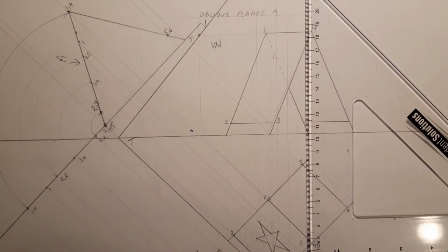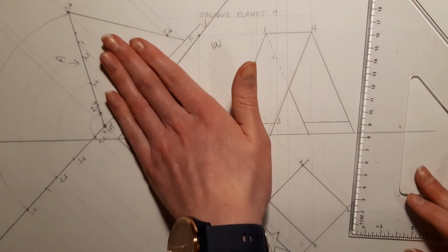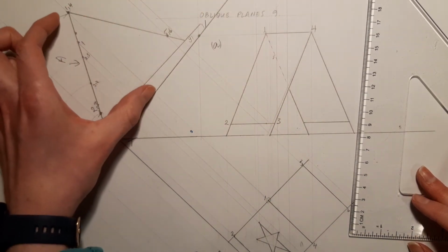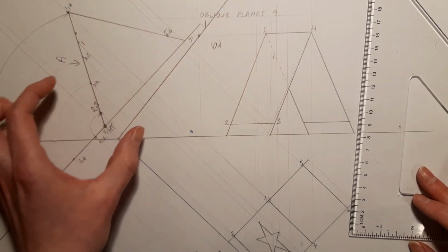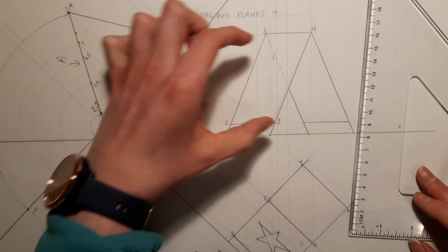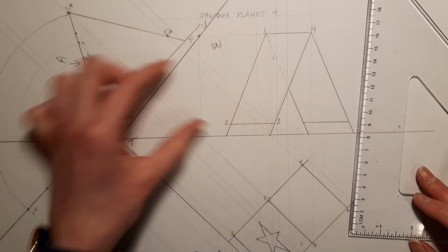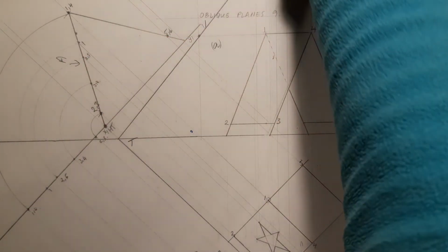And then you're wondering, how do you get heights? Well, if you remember, when I went out to my first auxiliary, I took this height from the elevation. So the heights that are in this view are the same in this view. So I can take the height of 1 and strike it on the line 1. I can take the height of 2 and 5 and strike it on the line 2 and 5. Take the height of 3 and 4 and strike it on the line 3 and 4.